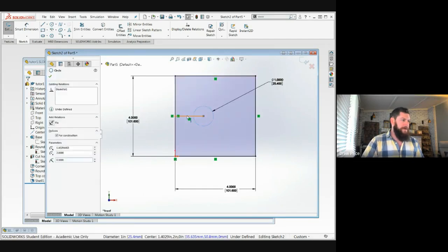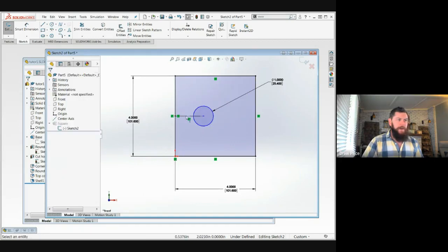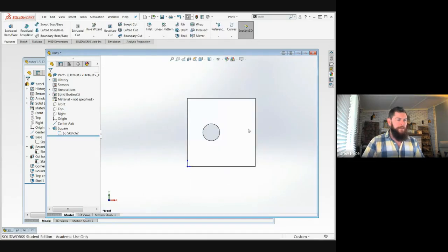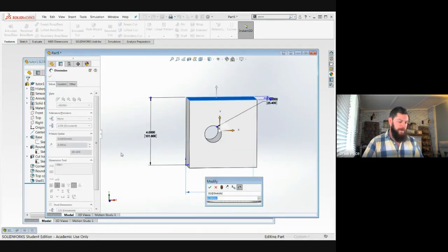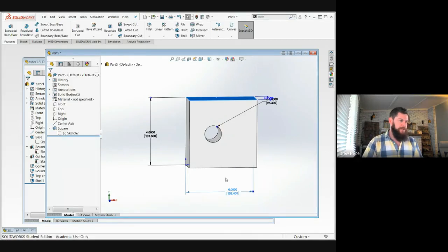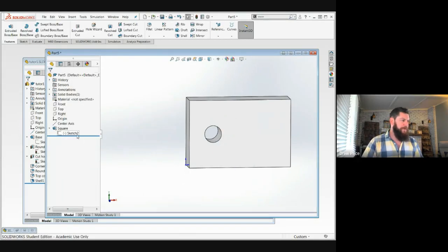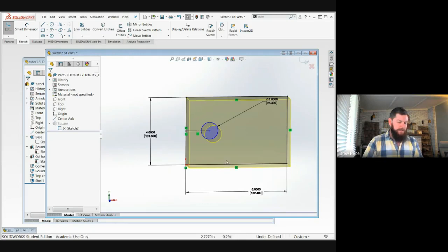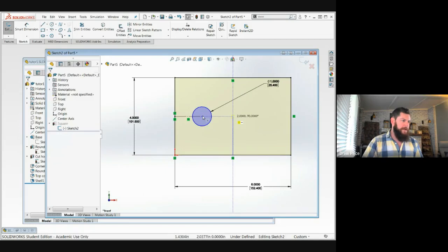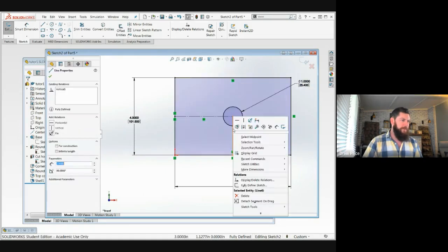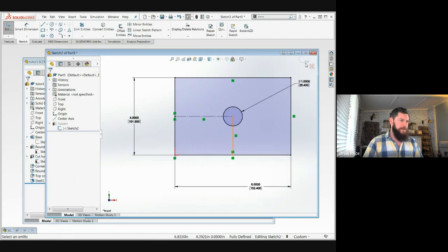And then if I swap both of these construction geometries, so my little leader line is now dashed and my circle is solid, when I create the part again, it leaves my circular feature dimensioned off the midpoint this way, but I can change other dimensions and rebuild the sketch and not move it around. So if I wanted that circle to stay in the middle of the block, I could do something like add another line on the midpoint here where they intersect, bring my circle over so it's now intersected with both of those lines that are now construction geometry.